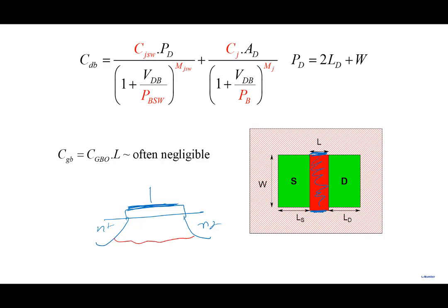And there are electric field lines from your positive charge here, and the positive charge terminates on negative charge in the depletion region and all that. But once you form an inversion layer here, your charges are all at the surface, and any change in the gate will only cause a change in the charge in the surface inversion layer. So nothing really happens at this particular point. The bulk no longer responds to the change in the gate voltage here.